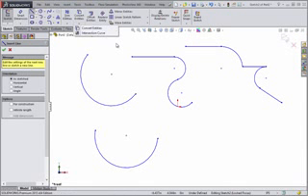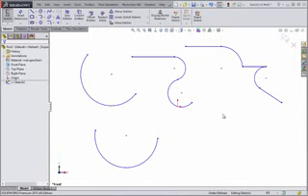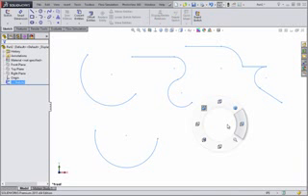To activate the circle command, I'm going to use another shortcut that I haven't used yet: mouse gestures. To use mouse gestures, move your cursor in any direction while holding down the right mouse button. The default sketch tools available are line, rectangle, smart dimension, and circle. It's important to note that different mouse gestures are available for each of the SolidWorks environments: parts, assemblies, drawings, and sketches. So if I exit my sketch and use mouse gestures, view orientation options display instead of sketch commands.